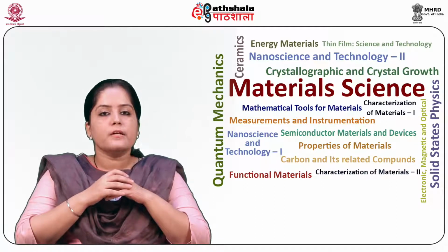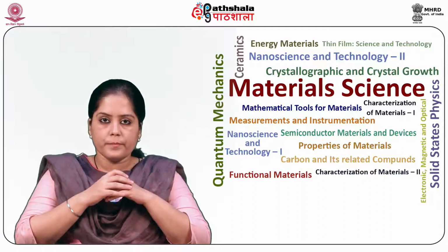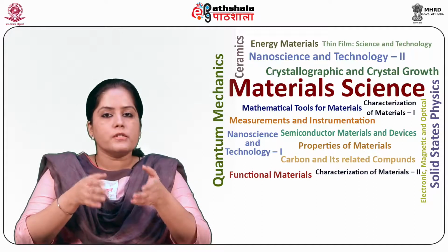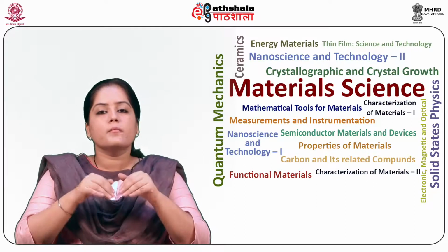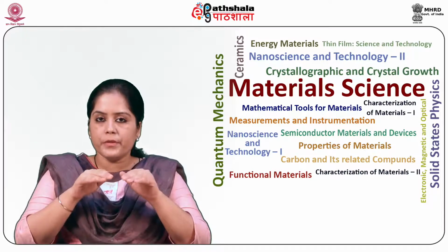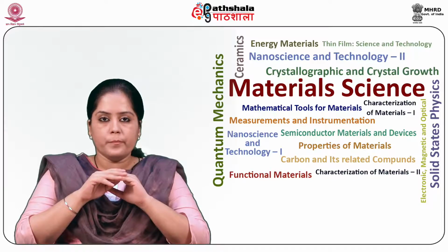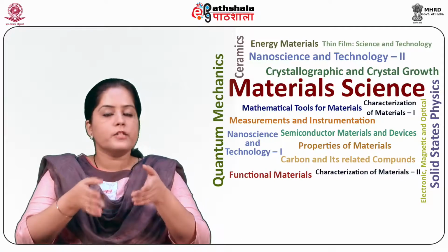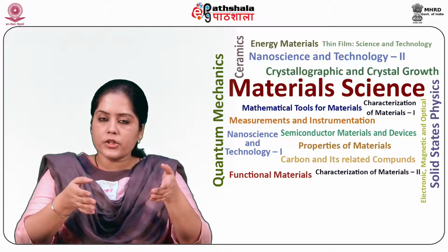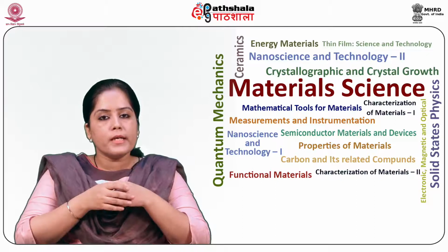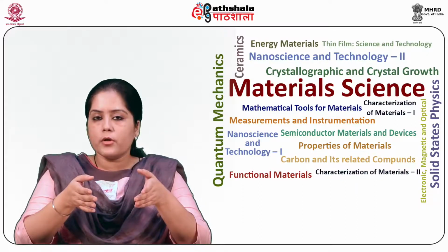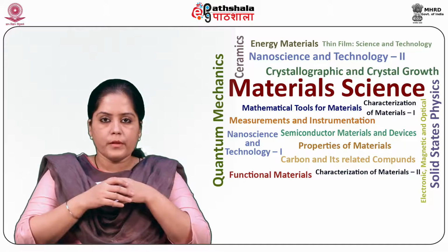Chemical methods may depend on the chemical formation of the film from the medium, and typical methods involved are electroplating, chemical reduction plating, spin coating, dip coating of a chemical solution, chemical vapor deposition, etc.